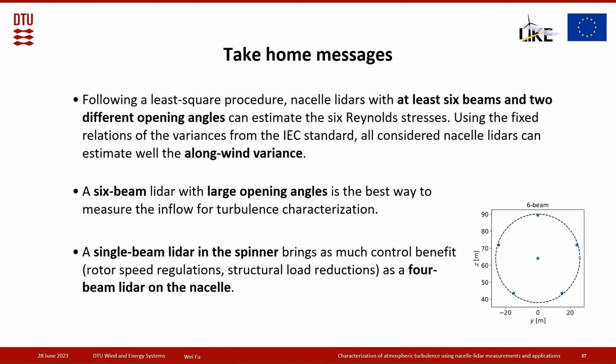And lastly, we have seen that a single-beam LiDAR in the spinner brings much more control benefit in terms of rotor speed regulation and load reduction than a 4-beam LiDAR on the nacelle.